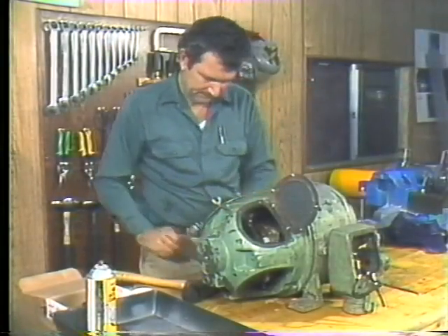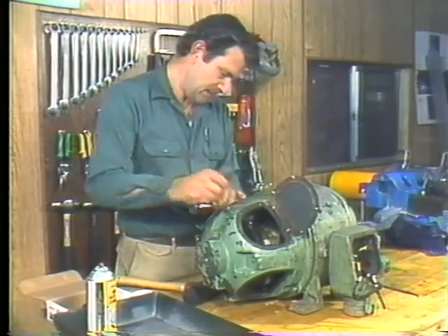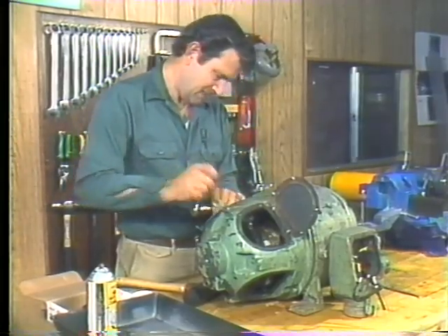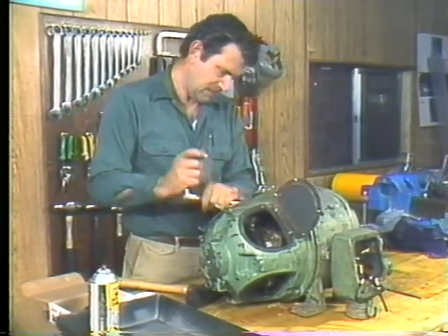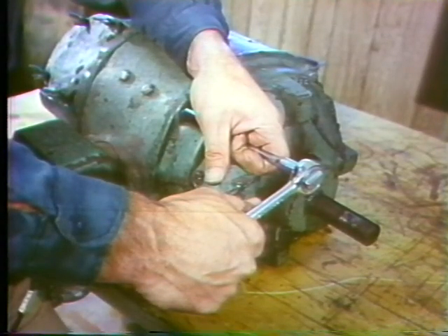Using the right size wrench, run the bolts so they're just snug. Don't put any pressure on them yet. We just want the bolts to hold the end bell right here. Okay, we repeat the same drill with the other end bell. Align it to the frame, tap it in, and snug up the bolts.